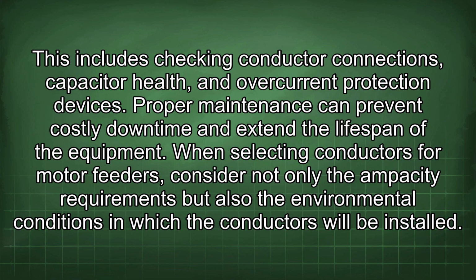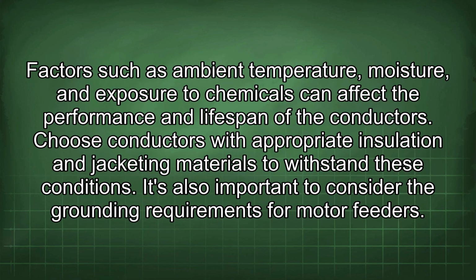When selecting conductors for motor feeders, consider not only the ampacity requirements but also the environmental conditions in which the conductors will be installed. Factors such as ambient temperature, moisture, and exposure to chemicals can affect the performance and lifespan of the conductors. Choose conductors with appropriate insulation and jacketing materials to withstand these conditions.